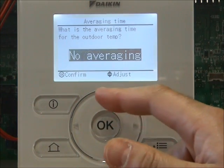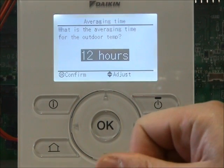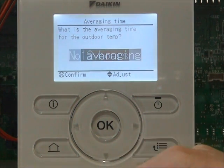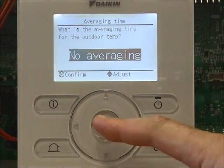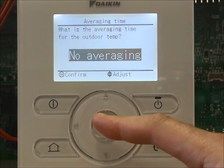If we had it set to 12 hours, it would do an average on the weather compensation every 12 hours, so it would only calculate it every 12 hours. If you have no averaging, it's constantly looking at the outdoor. So if your outdoor is influenced by sun or things like that, you might want to have the averaging set to 12 or 24 hours, so it adds up the averages constantly over a 24-hour period.